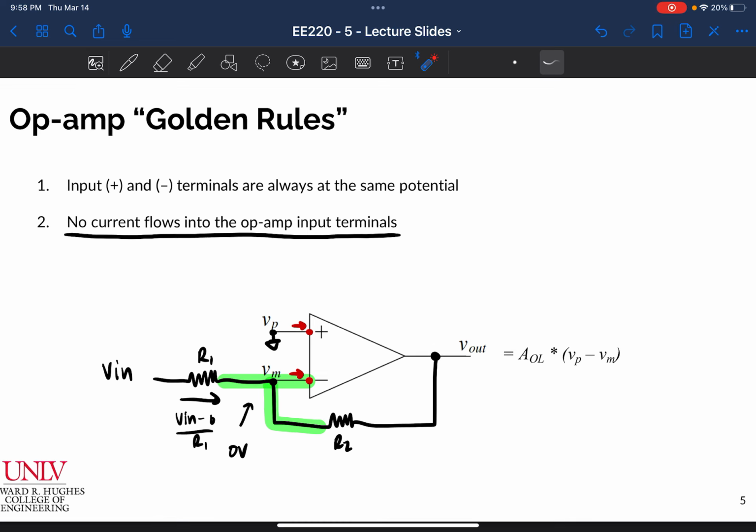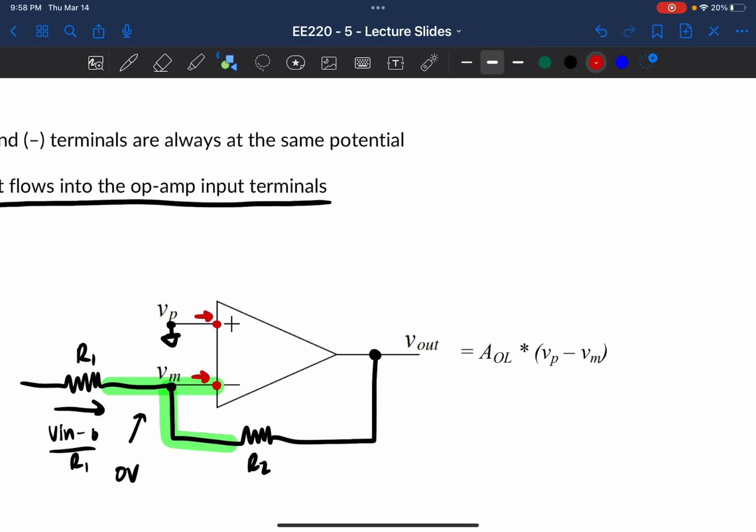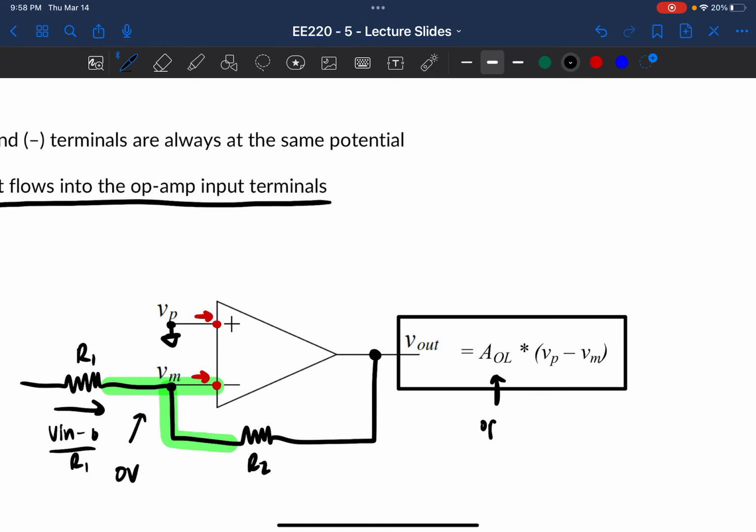And over here, I have this little equation, which basically tells us how an op-amp really behaves, what it's doing. This AOL term here is called the open loop gain of my op-amp, okay? Ideally, that value is very, very, very large because what the op-amp does is it takes the two input signals, VP and VM, and it takes the difference between them. There's going to be some difference here, and it multiplies it by some value of open loop gain, and that is what gives me my output voltage, right? Well, what did I just say?